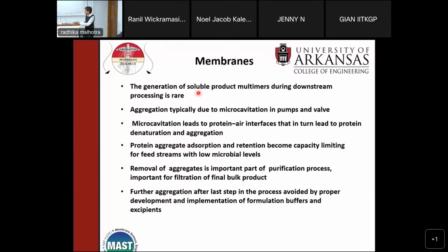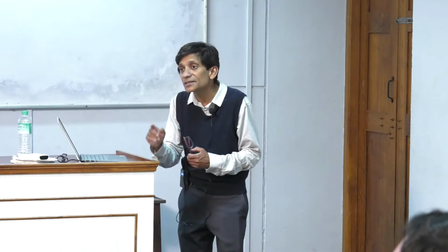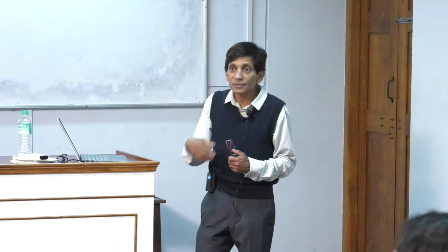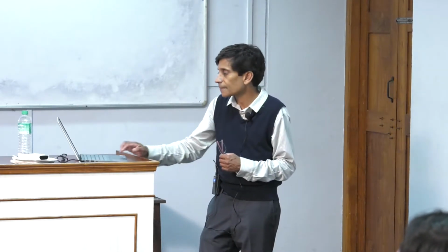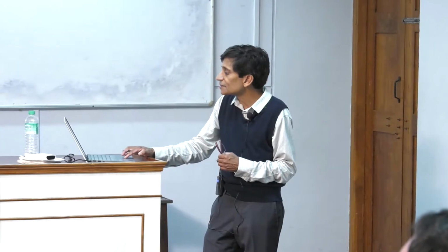But as I said here, generation of soluble multimers in downstream processing is rare. Aggregation is typically due to microcavitation in pumps and valves. Microcavitation leads to protein interfaces that in turn lead to protein denaturation and aggregation. I did mention earlier that liquid-air interfaces are very bad, okay, because they will cause protein denaturation. Protein aggregate adsorption and retention becomes capacity limiting for feed streams with low microbial levels.